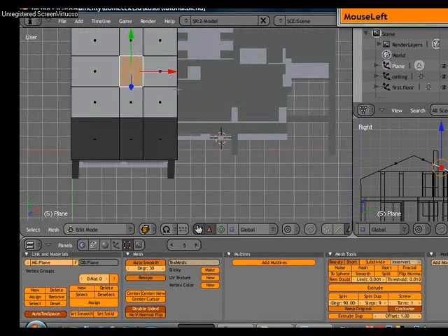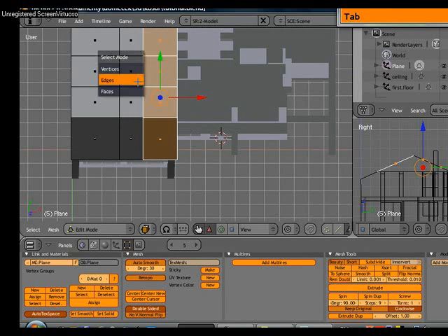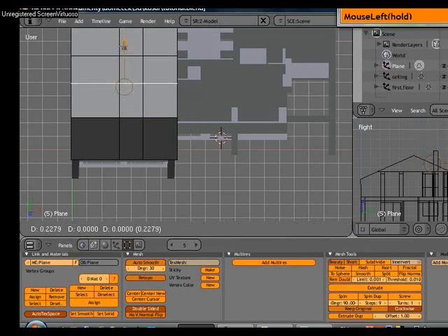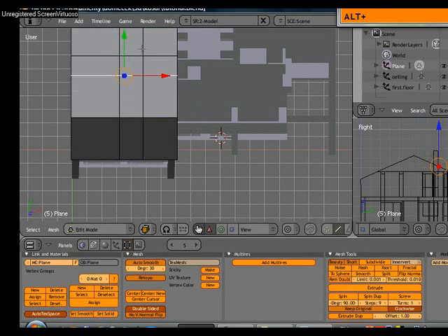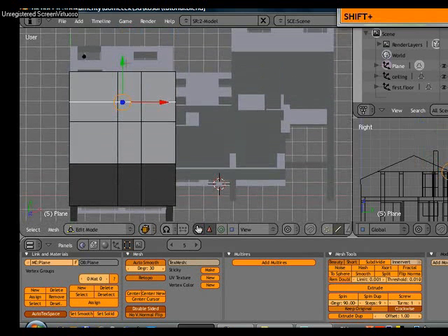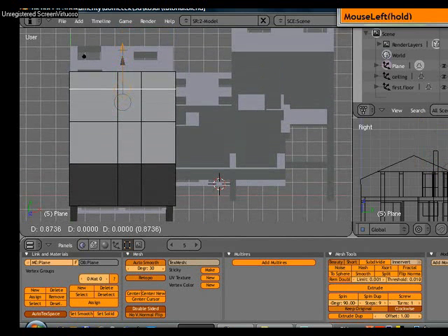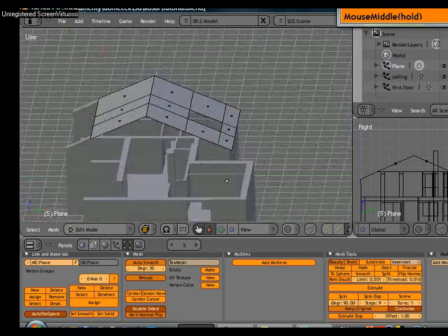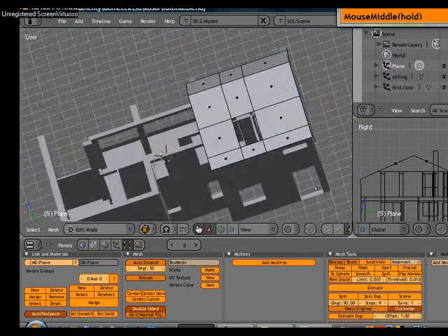So now I'm looking exactly from top on this face, and I need to switch the orientation of the transform manipulator to view mode. And now I need to go to edge mode. I select this edge loop. As you can see on the right part of the screen, I'm actually moving the edge along the side as well. So I can now select this face and delete this face, and I have created a place for a little window.